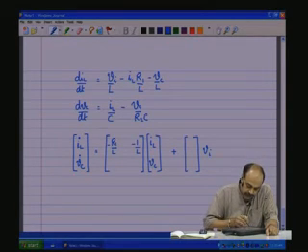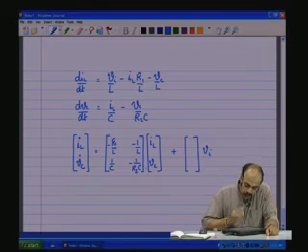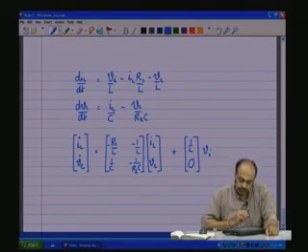Then for the second equation, dVc by dt, Vc dot equals IL into 1 by C, and Vc into minus 1 by R2 C, plus there is no Vi term here, that is 0.